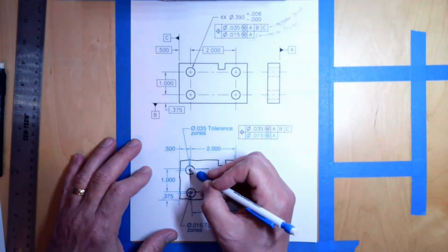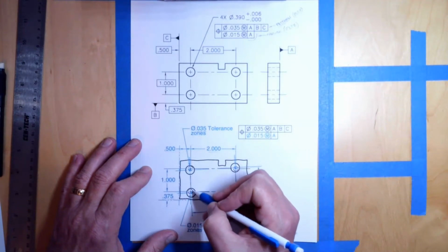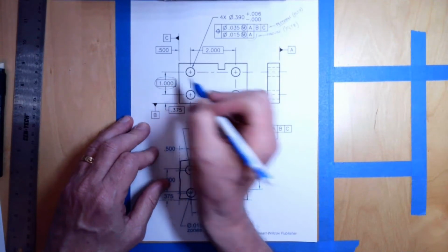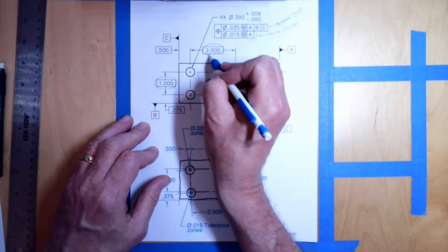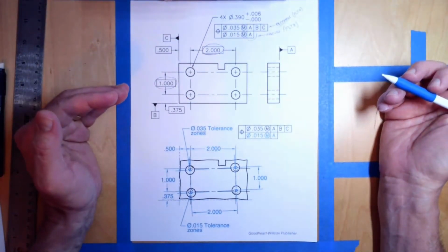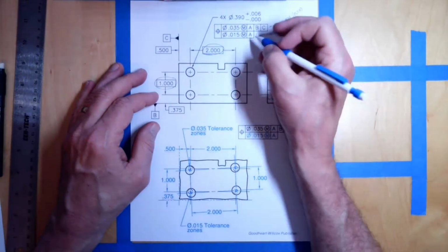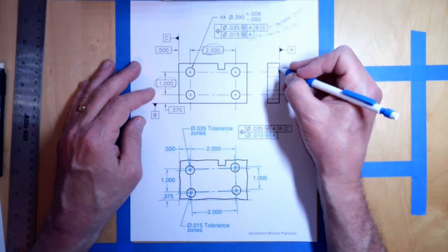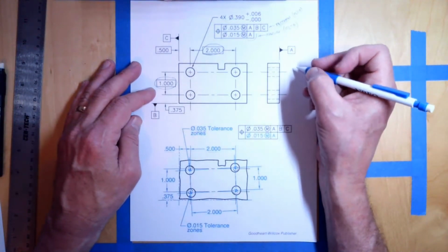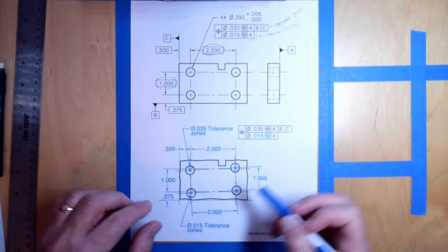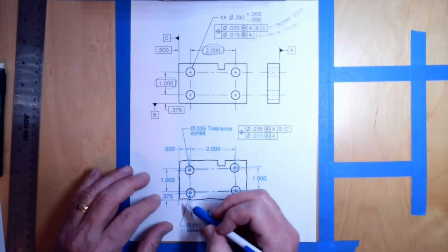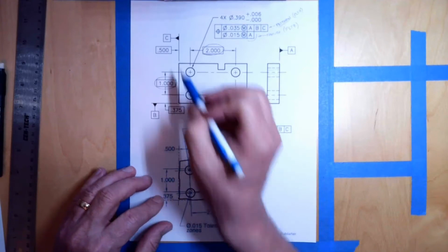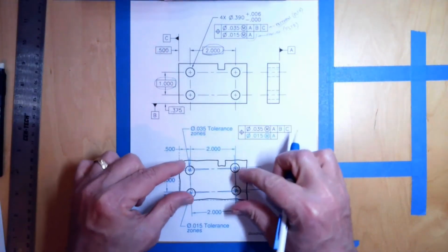The tolerance zones themselves are free to move within the Ø35 tolerance zones, provided that the feature locating basic dimensions are maintained. Okay, so this includes, because we have a repeated primary datum, the tolerance zones must be 90 degrees relative to A. But other than that, notice that it's a little bit hard to see here, but they are not constrained to B and they're not constrained to C.